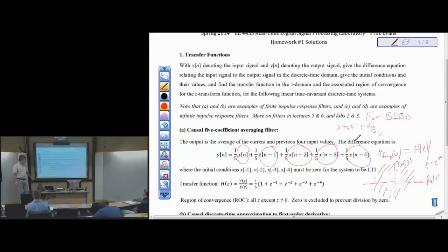There are some interesting things about this particular averaging filter. First of all, it's really good at what? What's a good application for this filter? Getting rid of or smoothing noise, reducing the amount of noise. It's going to take a running average. So if there's a little bit of uncertainty and jitter or additive noise among these samples, that gets averaged out. Not necessarily removed, but averaged out, reduced. In terms of a frequency response, this particular filter is a low-pass filter.